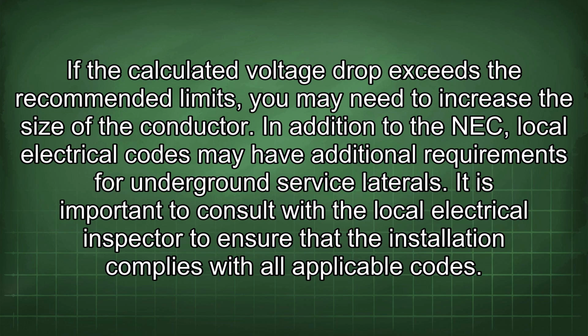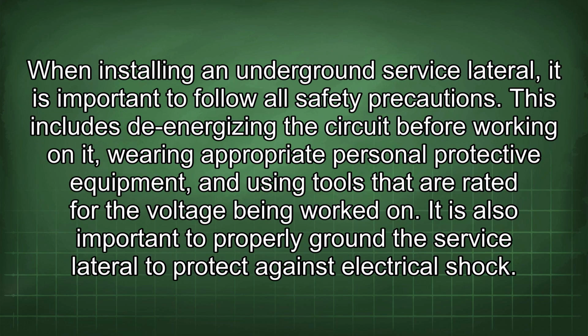In addition to the NEC, local electrical codes may have additional requirements for underground service laterals. It is important to consult with the local electrical inspector to ensure that the installation complies with all applicable codes. When installing an underground service lateral, it is important to follow all safety precautions. This includes de-energizing the circuit before working on it, wearing appropriate personal protective equipment, and using tools that are rated for the voltage being worked on.